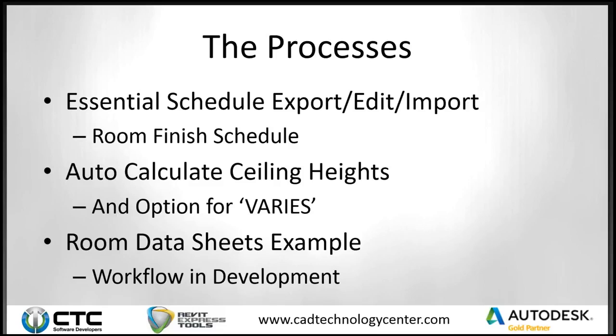This is a very simplistic example of a room data sheet, but I wanted to show you that with the power of Excel, you can actually do some pretty complex things in Revit. Revit understands a lot of information about a lot of different objects, and it understands a lot of those relationships. And some of those relationships, not all, because we just talked about the ceiling height to room height thing, but a lot of those objects we can actually get those associations through Spreadsheet Link and do some extra powerful lookups.